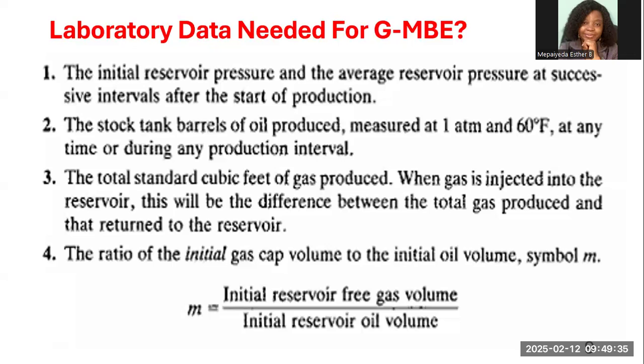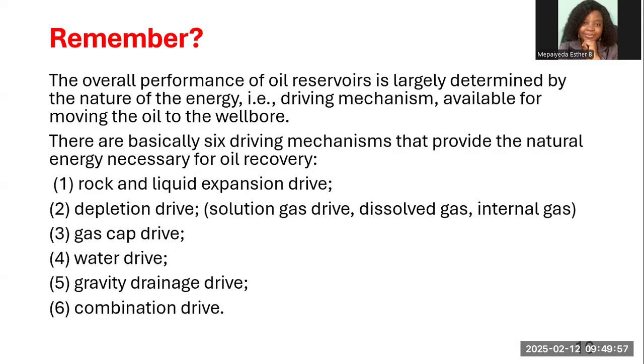Okay, and then fourthly, you need the ratio of the initial gas cap volume to the initial oil volume. That's your free gas volume to your reservoir oil volume. That's your gas cap size. Okay, your m is your gas cap size. So we'll see this as we go on. So these are the laboratory data that are needed for development of MBE.